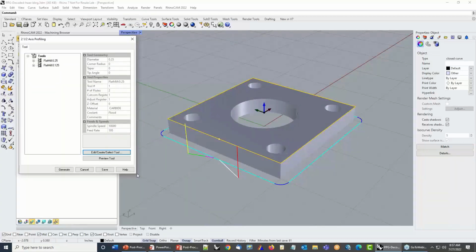Well, not necessarily. They don't have to be the same, but the general convention is that the registers will be the same. You can have a CUTCOM register that's different than the tool number. It's typically not done, but if you need that freedom, our system allows you to do it. In most cases, by default, when you're at the controller and you're going to do an offset, you're selecting a tool number. Like Joe mentioned, if it's different, you can obviously override that at the controller.